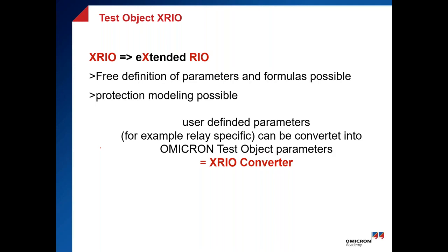No, I will now get all settings from the relay as it is: frequency, current, CT ratio, VT ratio, zone 1, zone 2, earth compensation factor for zone 1, earth compensation factor for zone 2. For each zone, I will have the settings, and based on the relay settings, I will calculate the relay characteristics. So I don't need to get the relay characteristic from the relay directly. I will get the relay settings, and then I will calculate the characteristic based on the settings.